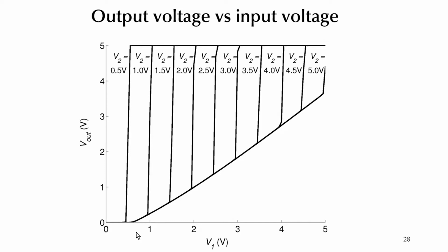And this is not possible all the time because it depends on where you put V1, V2, VB, and also V out itself, right? Whether you are actually tying V out back to the V minus, or whether you're running the transconductance amplifier open loop, right? And then what you see are these differences: if you go through the equations and write down which transistors you think are out of saturation, and then you solve the equations again, you would get the curves that you measure, right? Because what you measure is real. And it's also the kind of curves you get when Kirchhoff's current law is satisfied, because these are steady state responses.